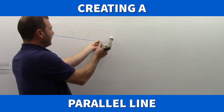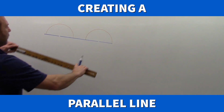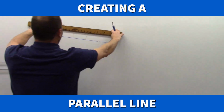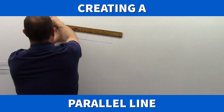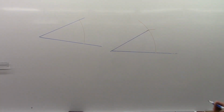Twice is the minimum. The longer the line, you may want to do it more often. And it depends on how long your ruler is. But 2 points for each point of your ruler. Now we're going to line up our ruler tangent at the very, very peak, the highest point of those arcs. And I draw my parallel line. Copying an angle.